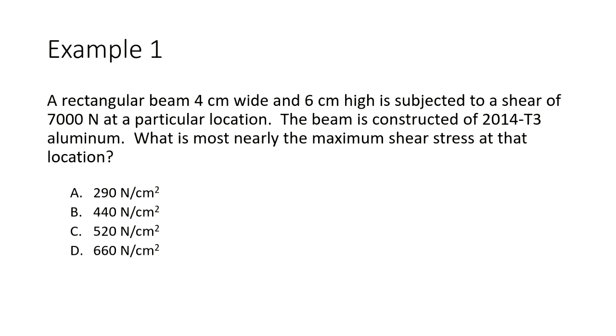It doesn't really matter in the problem. So think about it like this: if I have a bar, let's say I have axial stress, sigma equals P over A. If I got 100 pounds on that bar and it's 2 square inches, then the stress is 50 psi. It really doesn't matter if the bar is made out of wood or steel or concrete. Just sigma equals P over A.